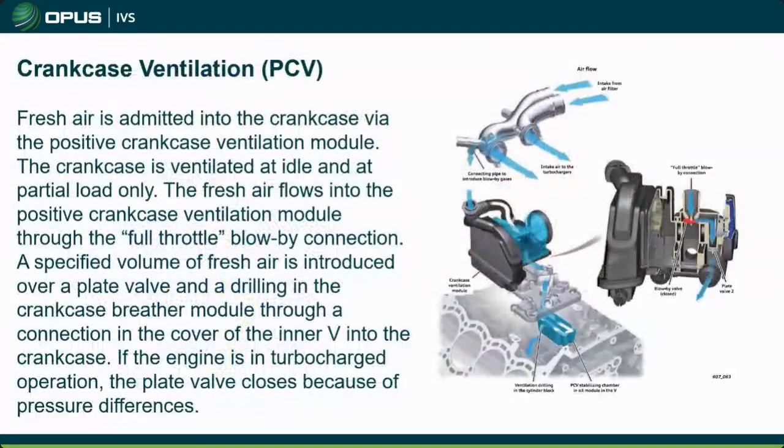So let's talk a little bit about how that ventilation takes place and when it takes place, because that can also assist with diagnosing, because this thing is not going to vent all the time, right? You guys can come back and read this word for word, but basically the gist of it is that at different pressures, it's going to vent differently. It's going to vent differently if you're at idle, than if you're off idle, than if you're at full throttle. In fact, this system does not vent at all if you're at full throttle.